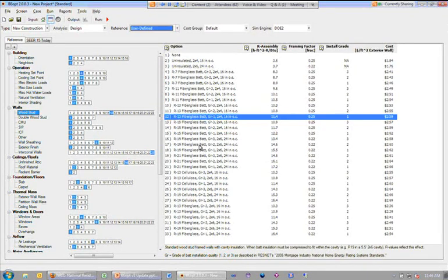So you can override parts of the automated references. We have that flexibility. Or, of course, if you're specifying a user-defined reference, you can go through category by category wholesale and completely make up what you want your reference to be. So we've got full flexibility on what your reference is. And if I didn't already say this, just for clarity purposes, the reference is essentially used for calculating energy savings and incremental costs on the output screen. That's its purpose.